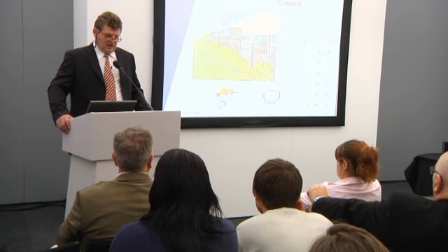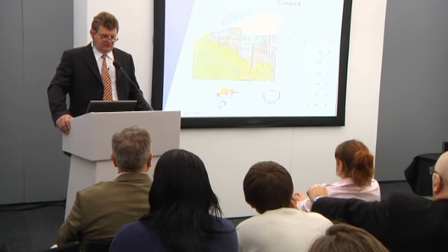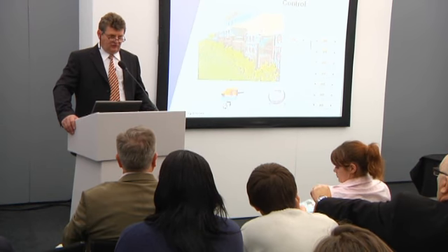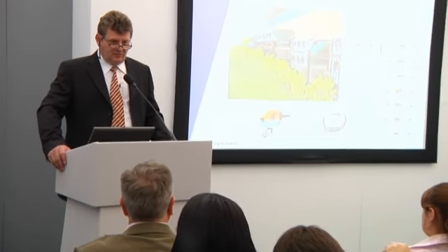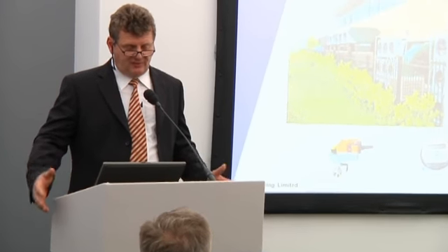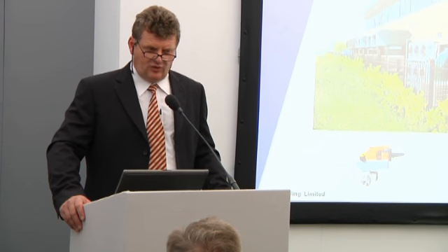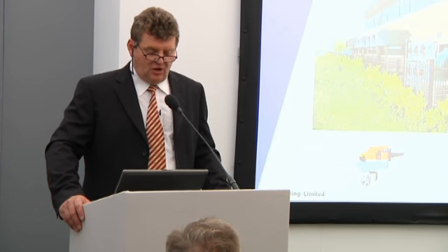How we control a computer room set is on two things: temperature and pressure. We monitor the pressure, in this case, of the underside of the raised floor, because we know if we're achieving 20 pascal of pressure in that underfloor, we're getting the right flow. A key part of commissioning is to understand how your raised floors are working and how your total flow rate of the server room is operating, what is required, and give it the right amount. Also, it gives us a control measure.